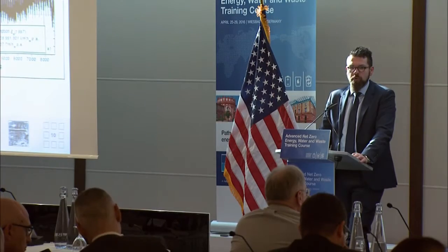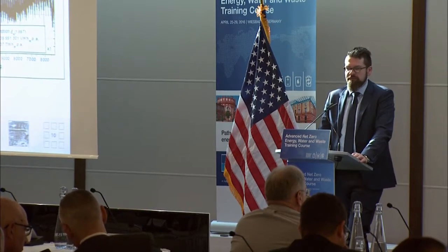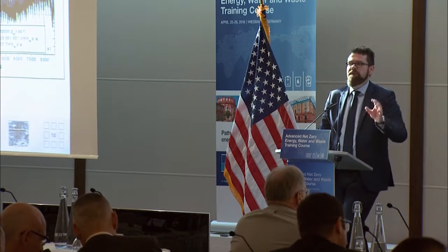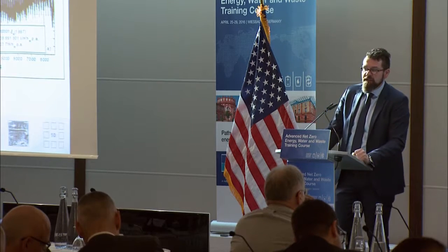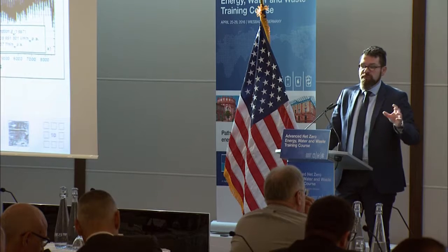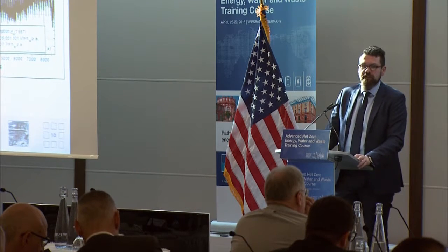So if we transfer this now to our comparison of electricity and space heating demand, you've got an explanation of why we have this, what we call bathtub shape of space heating and domestic hot water demand. All the buildings you integrate and connect to a central heating system, the same as in a central cooling system, end up with this load curve.